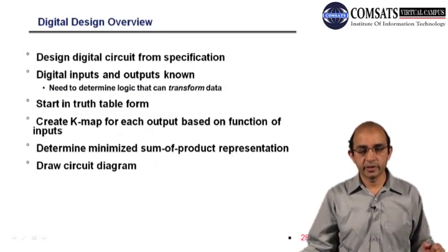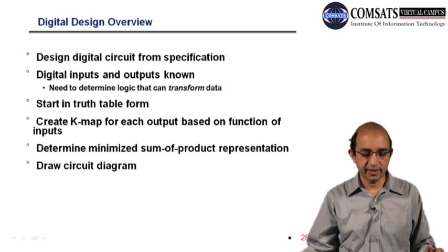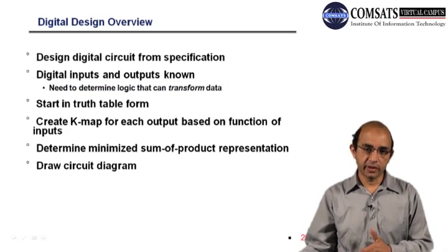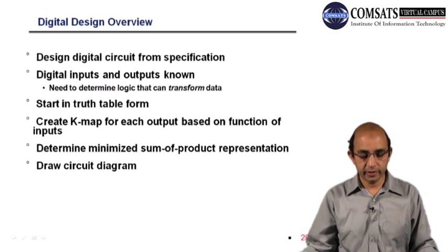Okay, so let's start the design analysis. You have to start from somewhere in order to design a logic circuit. Specifications have to be given in order to design a digital circuit. Specification means that the number of inputs and the number of outputs should be known. And then you can start from the truth table.